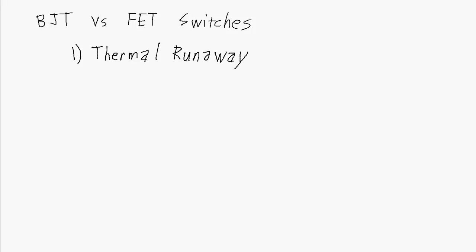Thermal runaway exists in all sorts of things, and it's basically when you've got a positive feedback loop where the heating up of some kind of device causes some other characteristic to change, which causes the device to heat up even more. So you get this positive feedback loop, and eventually that device is going to burn up, burn out, or blow up. For BJTs, the thermal runaway is exhibited in this way.